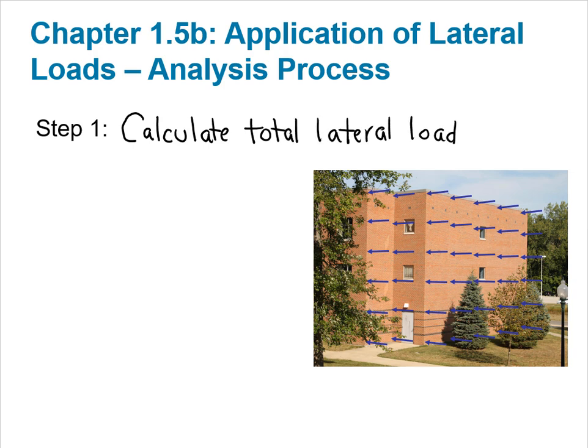If the structure is experiencing pressure due to loading like wind or soil, we integrate the pressure over the surface area to get the total force. If the structure is experiencing seismic loading, we probably already have the total force calculated. It is called the base shear. We then save the total number to use later.